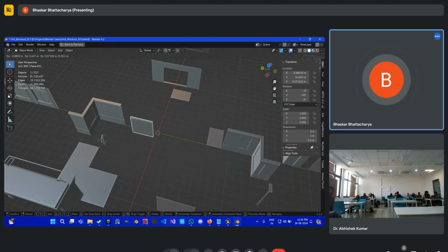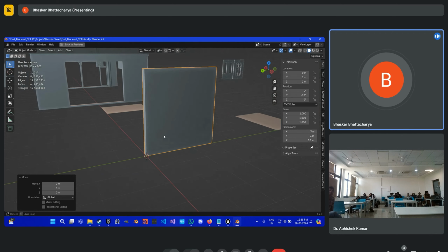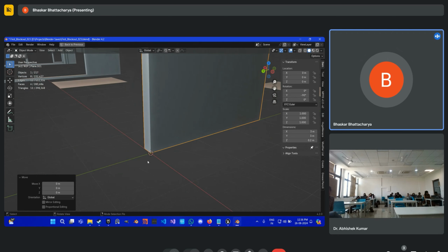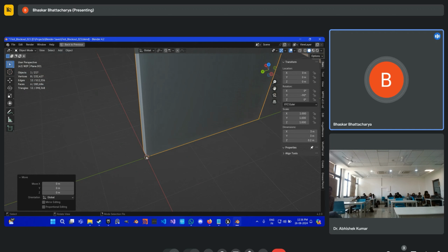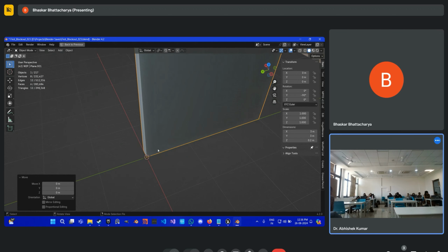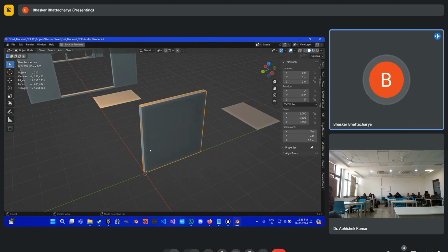Basically, you can just drag it. I just use some hotkeys to do that. But when I do this, you will see that this corner of this object is at the world origin. So this is where our pivot will be inside Unreal. You should know how to set this up from Blender, and this is the same thing for Maya as well.